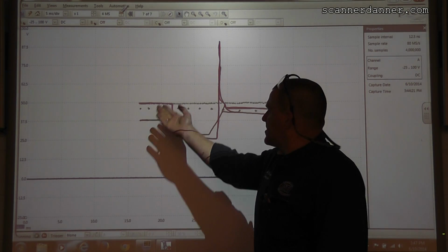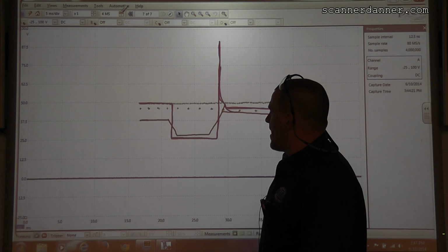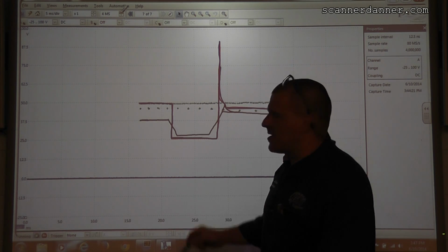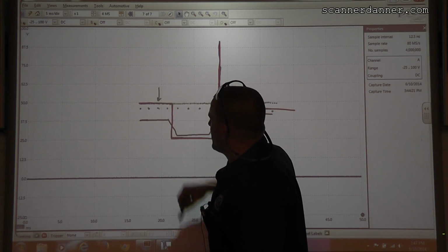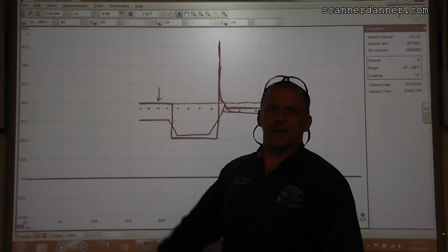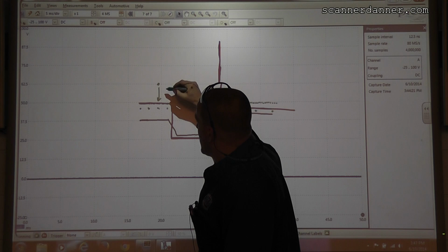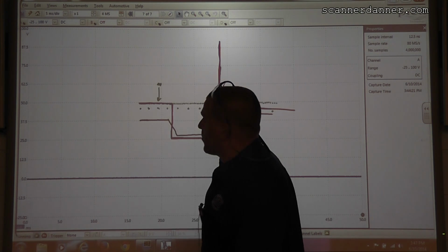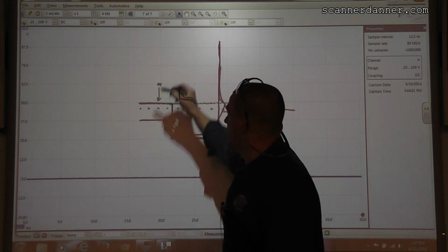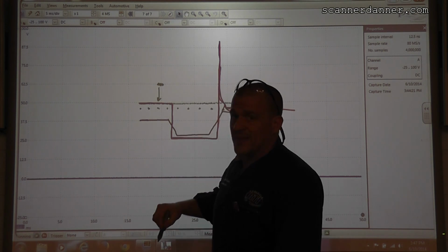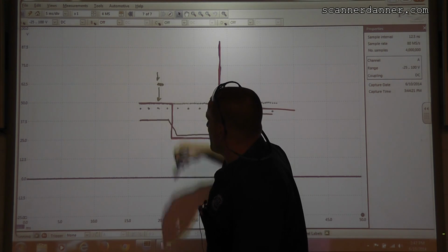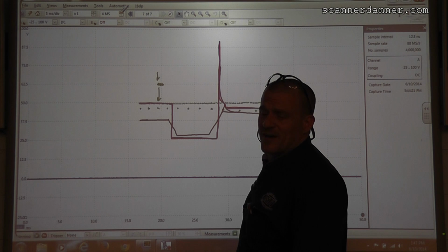What about sampling this signal more than what I have on this green trace? Imagine sampling, say, this point here 20 times. Would you need to? It would be good sampling it once, say here, and then sampling it again here. We're not going to miss anything. And then here again, we're not going to miss anything. Why would I want to sample that one dot 20 different times?